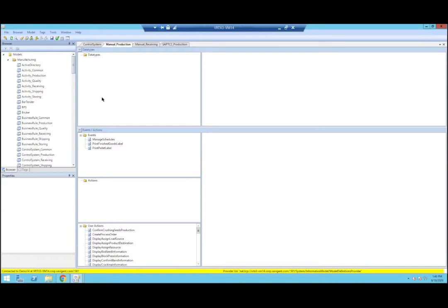So in our example that we just talked about, the machine state, maybe 0, maybe it's an OPC tag we're looking at. And 0 is idle, 1 is running, and 2 is aborted, something like this. What can happen in that translation layer is basically convert those into that enumeration data that we talked about, so that the workflow designer doesn't need to care about those implementation details on how the particular tool or machine operates, right? They'll only be interested in